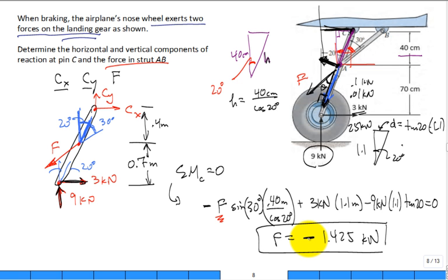I'm going to go quickly and correct my free body diagram. Don't do it. You'll be tempted. I remember when I was in statics, I was so tempted. Oh, now I'm going to go change my free body diagram. Well, then you're going to have to redo all your equations. Don't do that. Get your free body diagram and sort of seal it and just stay with it. And if some of your A's and B's and C's and F's come out negative, that means it's in the opposite direction of the assumed positive direction of that force or component of that force in my free body diagram.